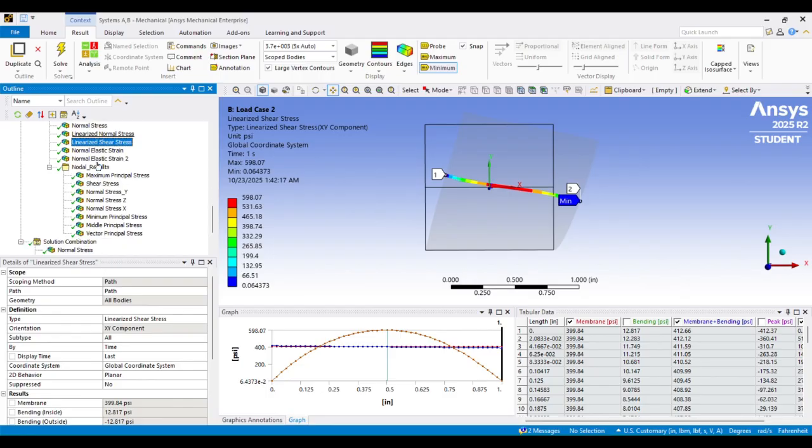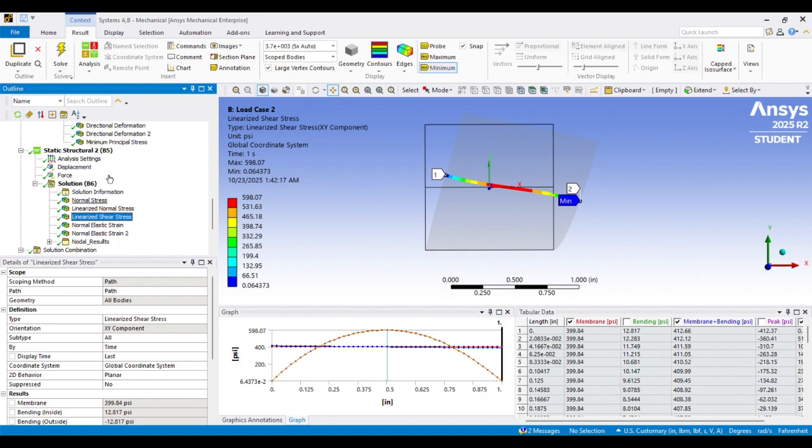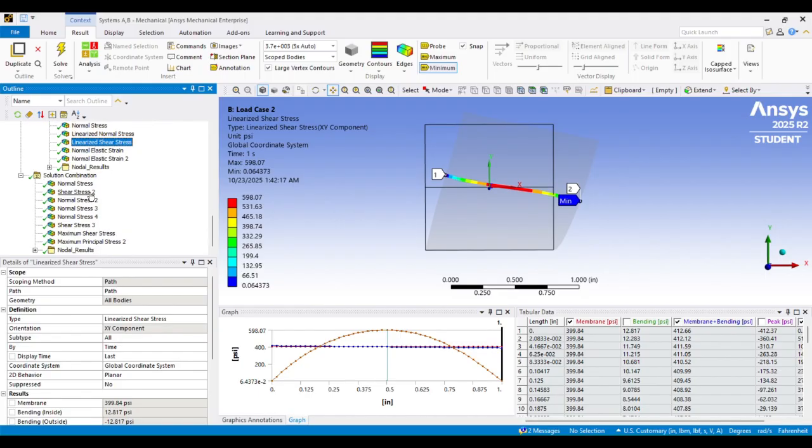So yeah, I wanted to add that just in case you, the viewer, were questioning why those stresses were what they were. And again, that's why it's important to go through these results and really make sure they make sense by hand if you're comparing them to hand calcs, just to make sure that you're validating how you loaded your FEA model and you validate your boundary conditions, and you get the results that line up with theory.